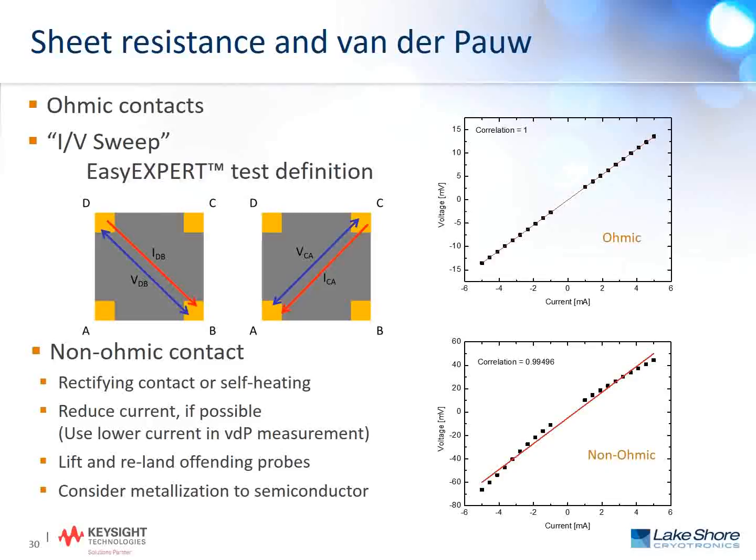So particularly at cryogenic temperatures, the self-heating is going to cause the carrier concentration and the resistivity of the material to change, not because of the material itself, but because of the contact. Now, when faced with a non-ohmic contact, there's a few directions that a researcher can go.